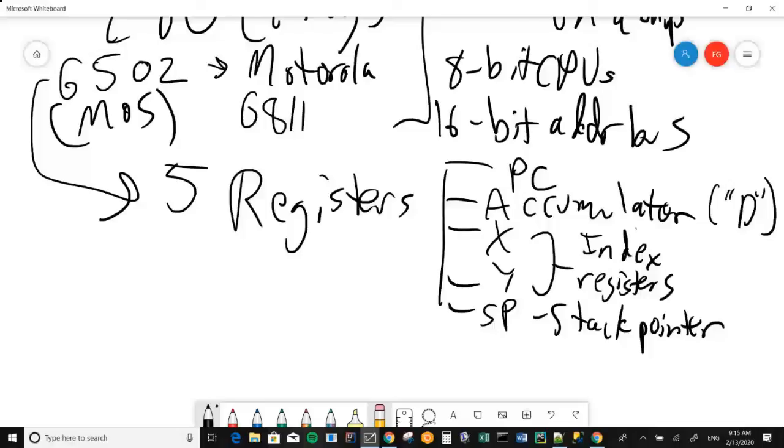But there we were. And I mean, on top of this, it also had an amazing sound chip, amazing for the time. So the sound chip had a 3-channel output, so you could play up to 3 independent melody lines simultaneously. And you would specify, it was actually a sound synthesizer. Again, just by storing data in memory that's been mapped to the sound card, which in turn was wired directly to the speaker, you would actually specify the complete waveform of the sound that you wanted.